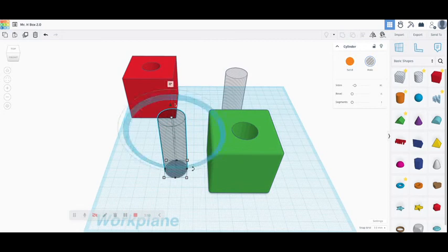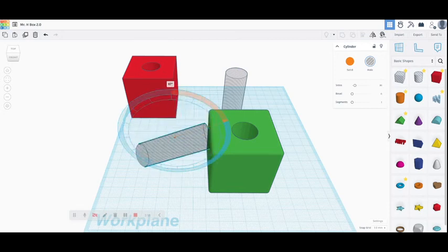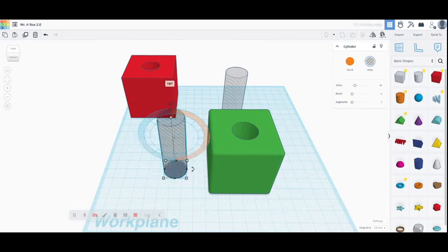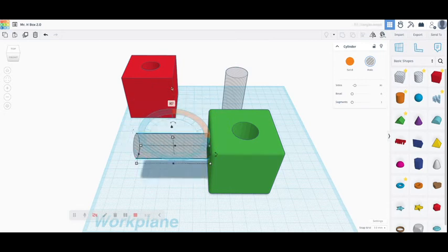Now what we want to do is use a new feature, which allows us to rotate the cylinder. If we grab those arrows and rotate, we can have it go in 22.5-degree increments. If we hold the mouse button down and bring the arrow out, we can do it in single-degree increments. And if you need to, you can always type in the exact angle, just the way we do a normal typing of numbers, and get an exact measurement by typing it in manually. So I'm just going to make that 90.